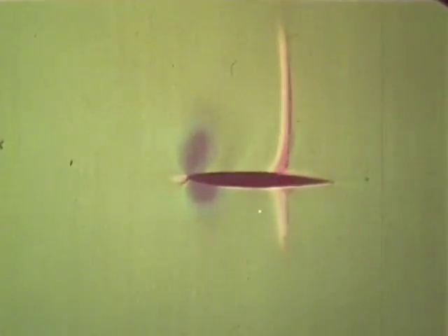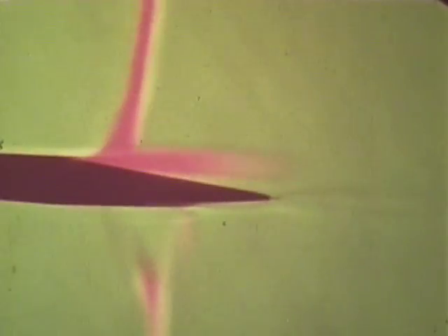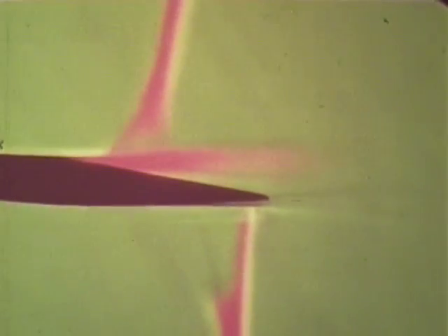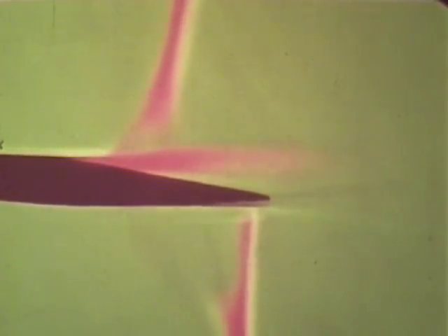Let's stop the picture a moment. Here is the supersonic region shown in a lighter green. The flow everywhere else is subsonic. As the airspeed is increased, a lower shock appears. Both shocks start to move back. Then the upper one stops because the boundary layer breaks away from the surface with a lot of turbulence. This is called flow separation.